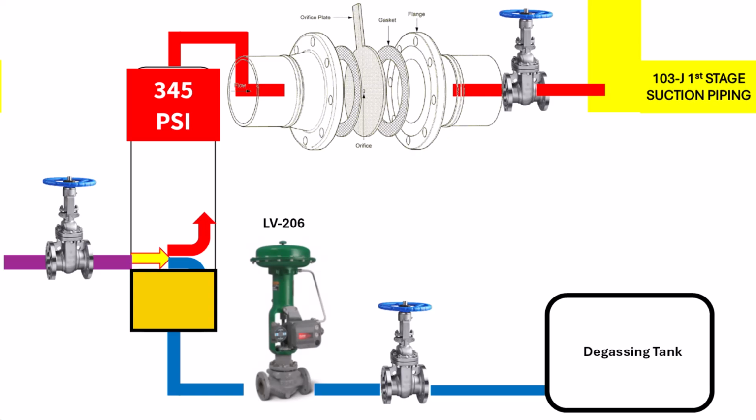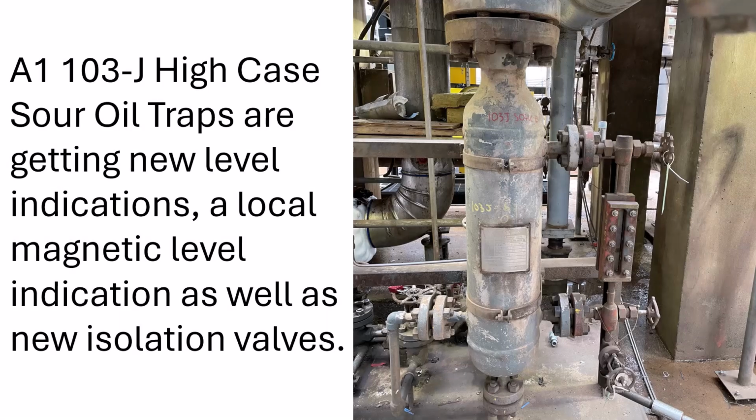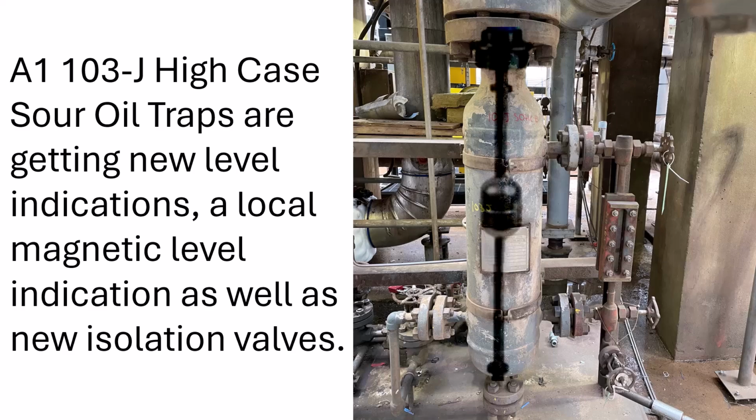As we just learned, keeping an appropriate oil level in the trap is critical to the system working correctly. How do we know what the level of oil is inside the sour oil trap? The answer to that is changing, which is what this MOC is about. The way the level is currently identified is with an internal float mechanism, which is not the most reliable technology to use for this application and is difficult to work on.